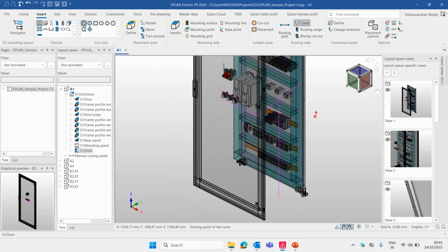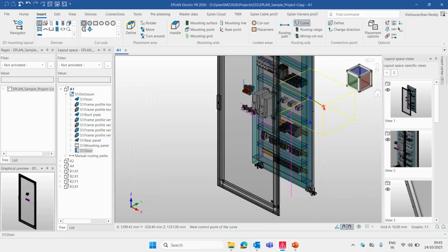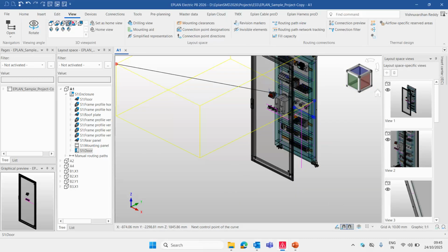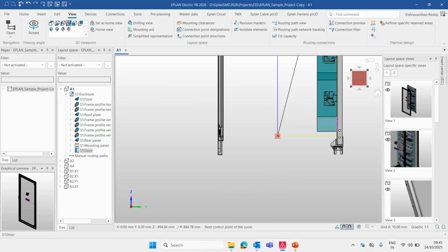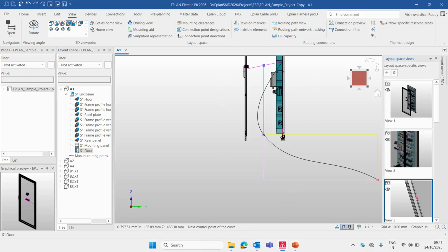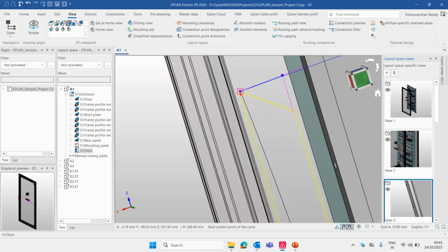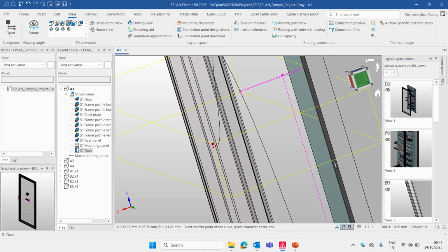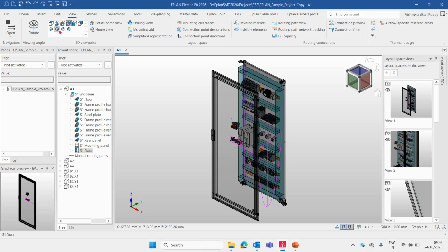Now I will select my first point in the panel. After that, I will go to this view. I will hit on this Right. Okay. I will select the second point which is here in this. And after that, what I do, I will again double click on this layout space view and I'll select this third point here. It turned to blue. I'll click on this and after that, I'll hit a space bar. Once I hit a space bar, now you see that all those views are coming and I'll click on this home button. Automatically, it will take me to the Southeast isometric view.